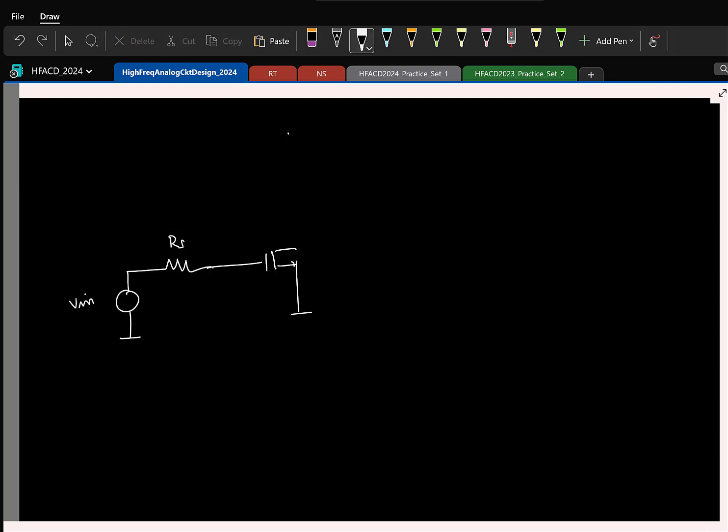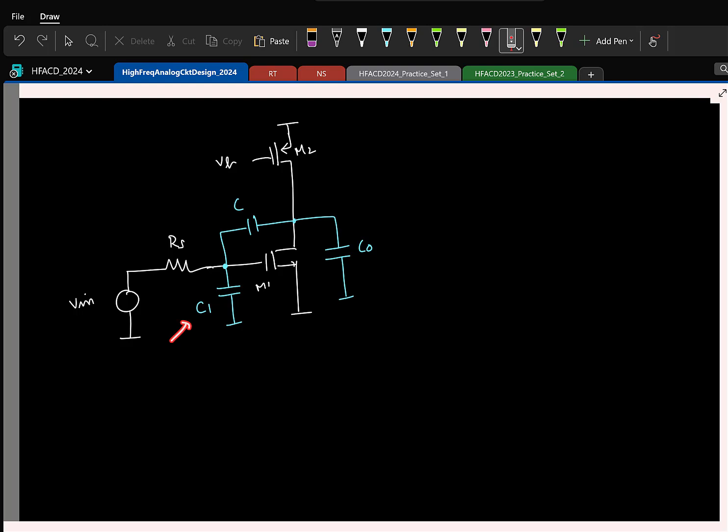Basically, it's applying KCL and doing it. Let us say we have a PMOS current source as the load, M1, M2. So you can consider all parasitic capacitors here, right? So you will find that you will have a capacitor C1 here. So first of all, just tell me what all parasitic capacitors will contribute to C1? Only CGS of M1. What about CGD of M1?